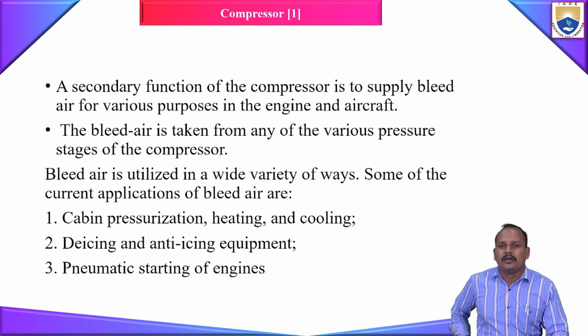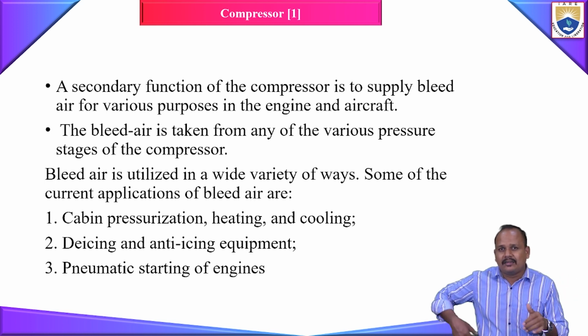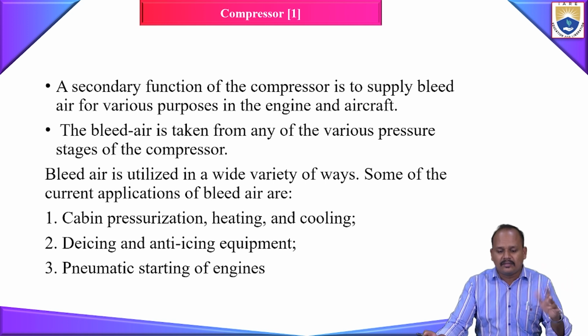Another important application of your bleed air is the cooling of your turbine blades. See, the combustion chamber is a static component, so we provide a certain amount of cooling. Even with the cooling, the air entering the turbine will have a temperature of around 1300 to 1400 Kelvin. At 1300 to 1400 Kelvin, it is entering a rotating component, not a stationary one. Since it is rotating, you will already have a huge mechanical stress. When the high temperature gas enters, it is going to increase the stress on your material once more.